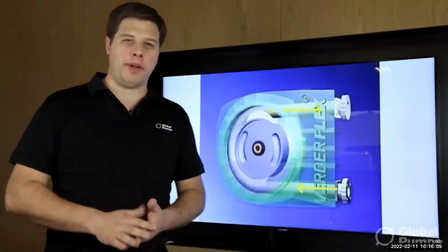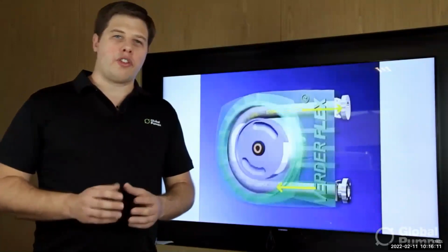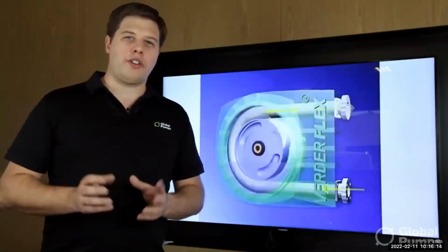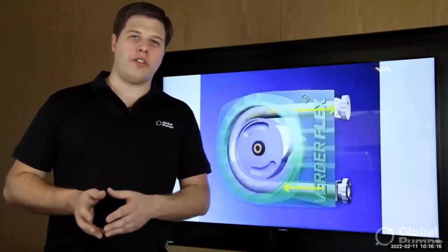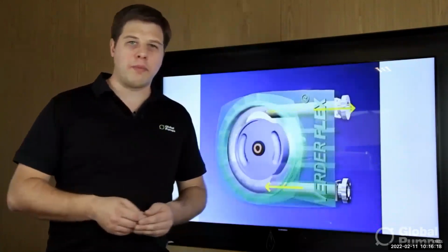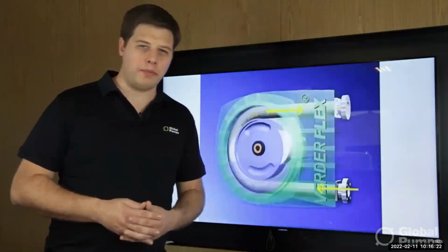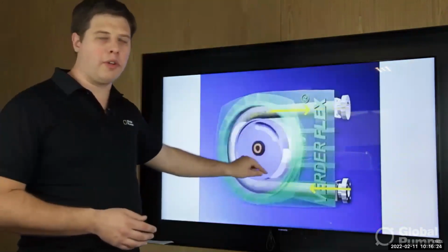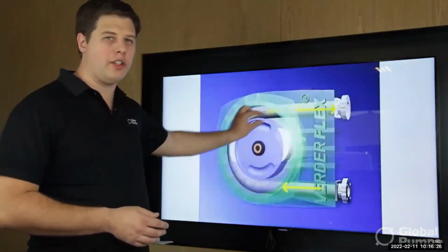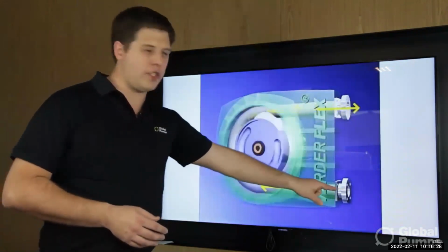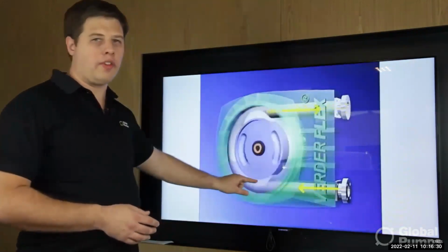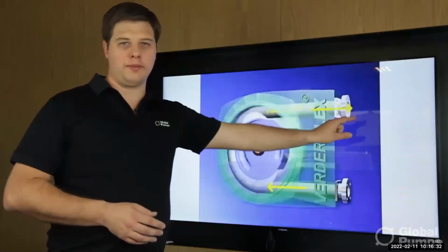A positive displacement pump is a pump that traps a fixed amount of liquid and transfers it from the suction side of the pump to the discharge. So what we have here is a rotary positive displacement pump. We have a rotor with pressing shoes that press against the hose, and it transfers the liquid from the suction side to the discharge side.